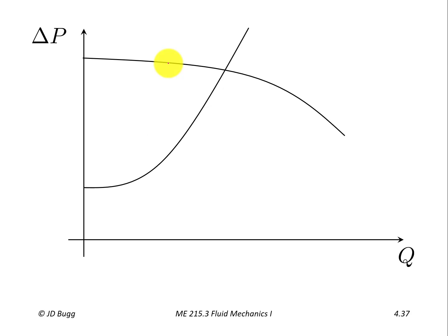Now if we take a look at the other possibility, and that's changing the fixed system pressure, if we change either of the two terms in the fixed system pressure, what we're doing is taking that system curve and shifting it vertically. So here I'll show what happens if we shift it downwards. Now in practice, what is one of the ways we could shift the fixed system pressure downwards? Well, if we have the exit of our pipes, Z2 at a particular elevation, 100 meters higher than Z1, let's say, and we were to move it downwards, then we're reducing our fixed system pressure.